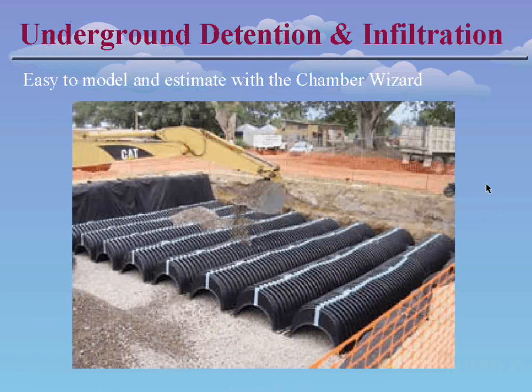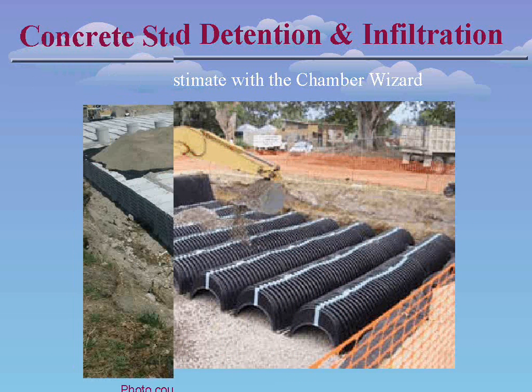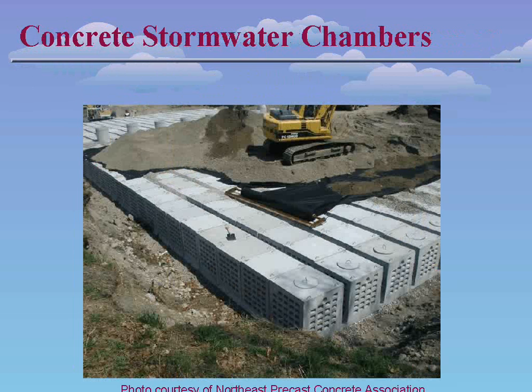Most underground detention systems will also have an infiltration component or exfiltration where you're intentionally leaching water into the surrounding ground, and that's typically modeled by setting up an exfiltration outlet on the pond. That gets us into outlet devices, of course.